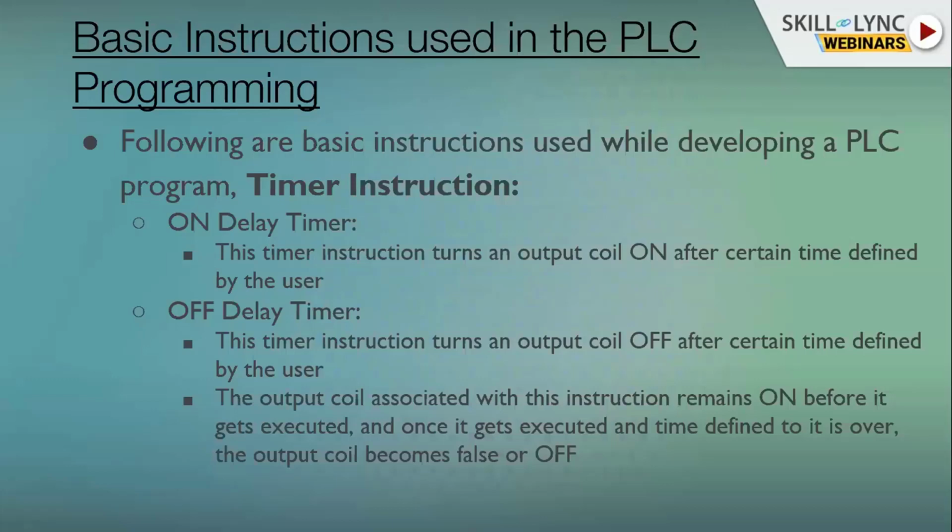Suppose we are in a food processing industry, filling water bottles. You need to have the bottle just below the water pipe for, let's consider, 2 minutes. This timer helps keep the bottle there for 2 minutes. First, the fact that the bottle has stopped there can be known through input devices like limit switches or sensors.